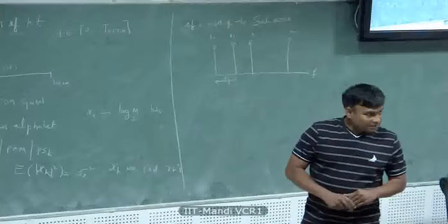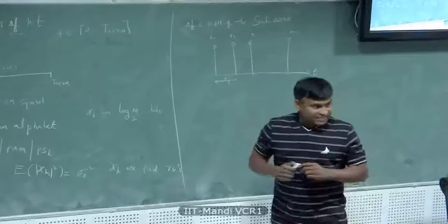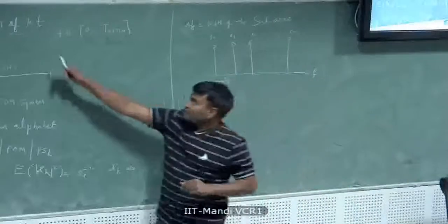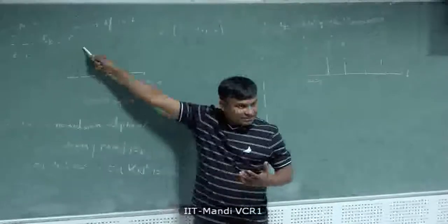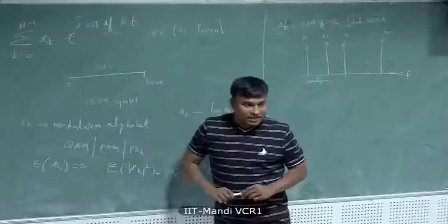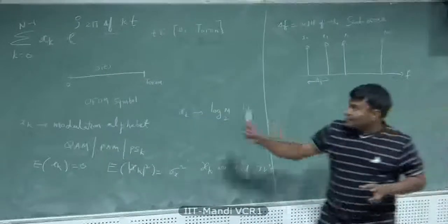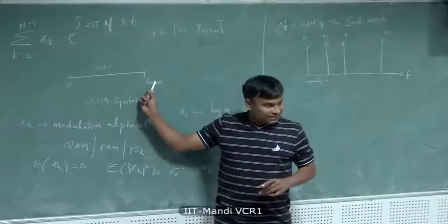Whereas this is a multi-carrier system. Why do we call it multi-carrier? Well, what are the carriers here? The carriers are these k times, these are the carriers. The complex sinusoids are the carriers. Unfortunately, the spectrum of this complex sinusoid is not a delta function, is it? No. Why is that? It is limited to 0 to T OFDM symbol.